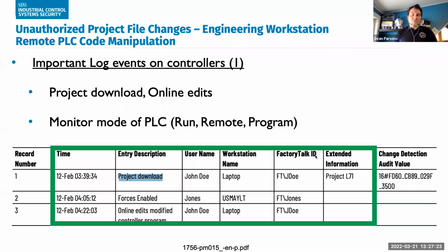So the best practice, of course, here is to make sure it's in run mode unless you have to program remotely. Sometimes these changes do not occur on a regular basis, and not often. So having it in run mode is the safest bet. When you know there's a change, getting on site or having someone flip to remote mode can be that protection you might need from remote adversaries accessing the PLC. Now, the other mode, of course, is program, where you're actually programming the controller, and the controller might be stopped at that point. So nothing is running in the controller at this point.